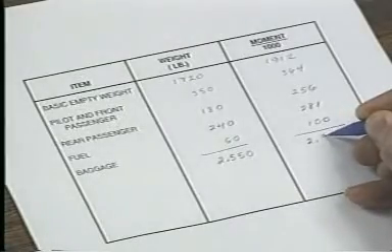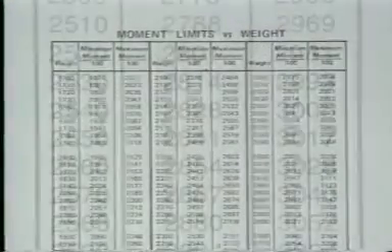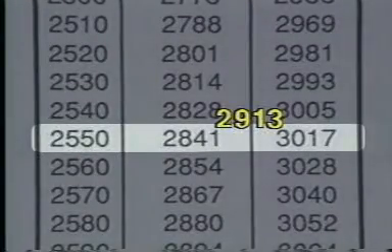Once you've finished totaling the weights and moments, you can use the moment limits versus weight table to determine if you're within limits. Here, you must find your loaded weight and then verify that the total moment is within the minimum and maximum limits.